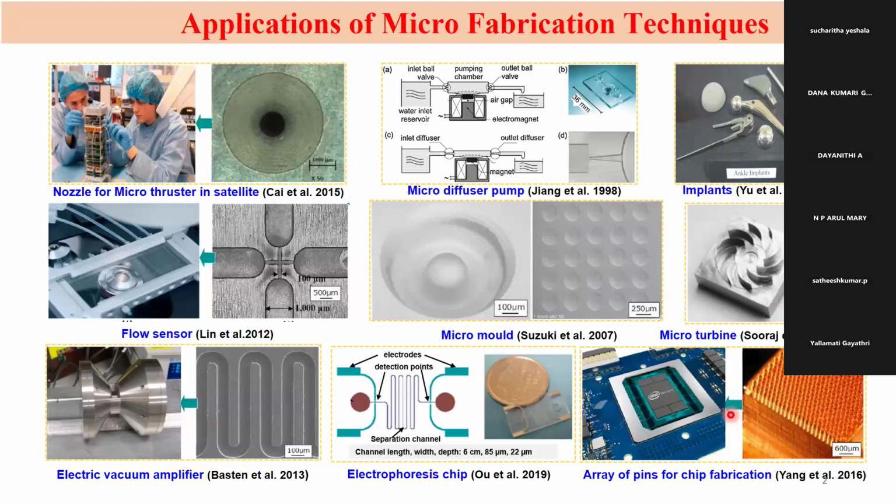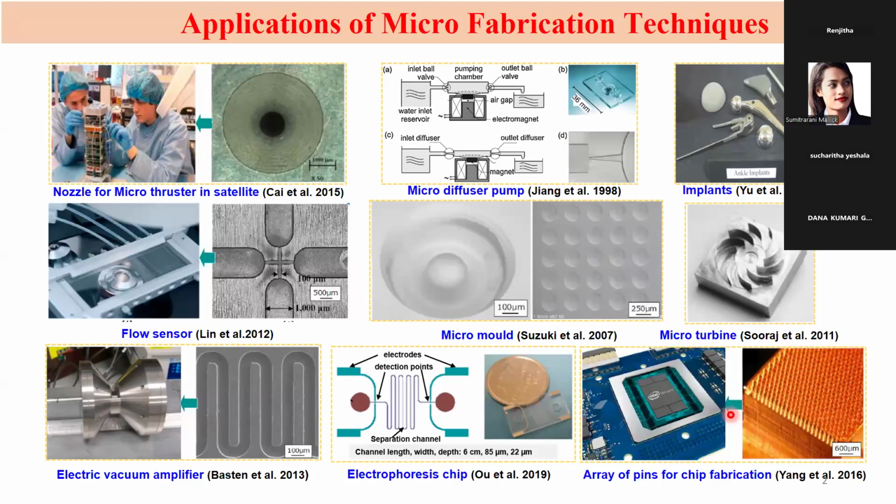That means, let's say we have a small chip. For that we need to dissipate heat, for cooling applications. So for this we make some array of micro fins. These are majorly fabricated by the micro milling process, and we can say the micro machining process.